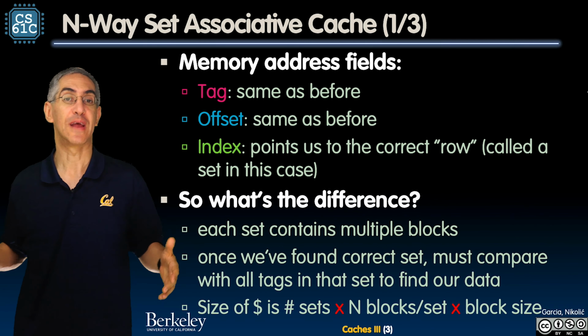Even a two-way set associative handles all those conflict misses. Copying from a blue to a blue is great. Now, copying from a red to red or green to green, I can fit both reds or both greens there. So that kind of copy from one to the other really helped, even while just moderately allowing for two-way, just a little dribble. Here's direct mapped. One step over is two-way. By the way, n almost universally is a power of 2. It's 4-way, 8-way, 16-way in general, okay? And again, hardware isn't that bad, only need n comparators. So 2 comparators, which is great.